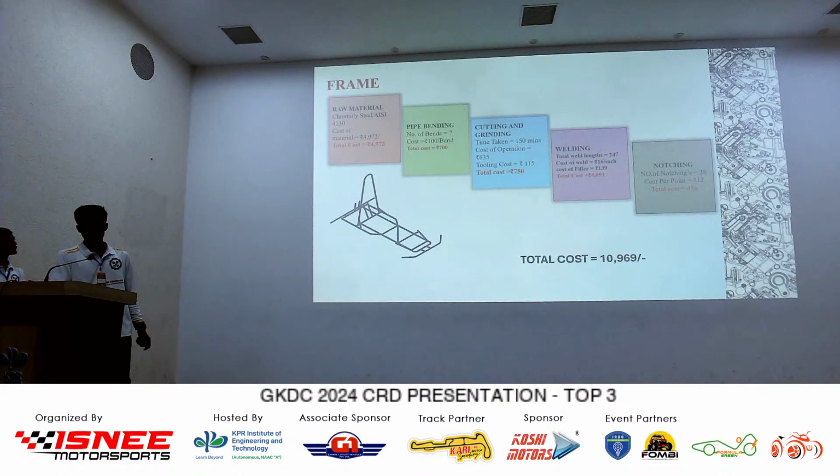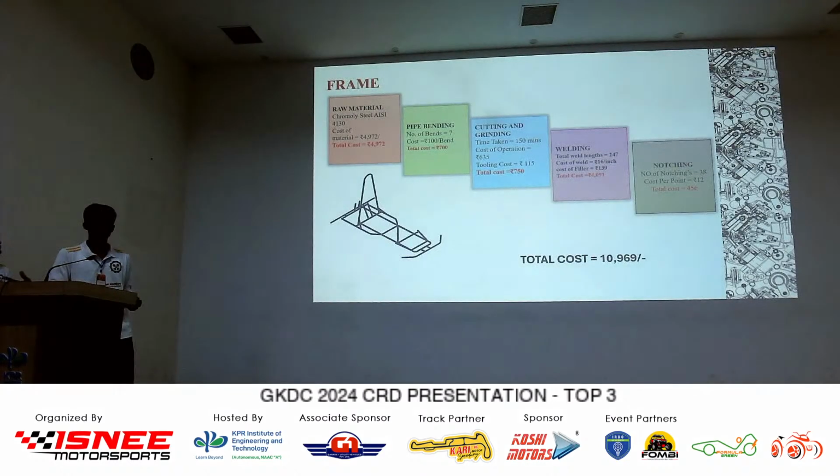Next, coming to the first one, frame. For the frame, we have used alloy steel AISI 4130 grade, seamless. The total cost for raw materials is around 5,000. Next, the processes used in the chassis are pipe bending, cutting, welding, and also notching. For pipe bending, we have a total of 7 bends. For each bend, it costs us around 100 rupees, so the total will be around 700.